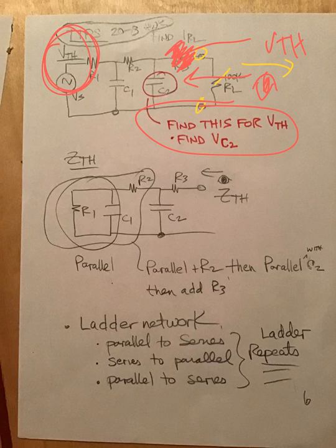When you're computing Thevenin here, Thevenin requires you to put your eyeball out here and look in and compress the battery, and here's a circuit that appears to have a parallel relationship away from where your eyeball is.